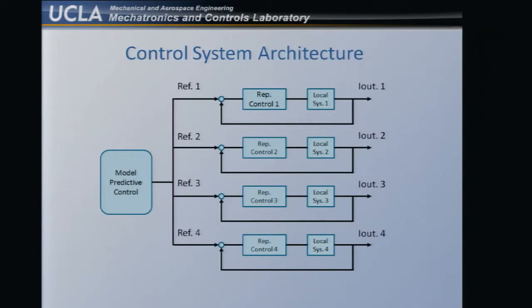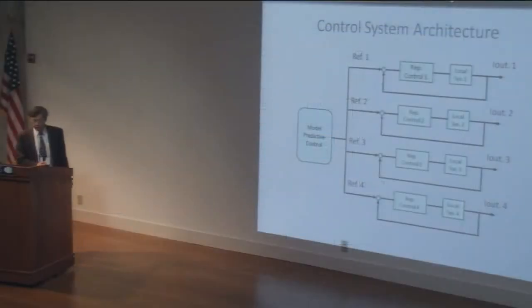In a sense, that control algorithm is able to do what the previous speaker talked about, like harmonic tracking and rejection of unwanted harmonics. In a more control block diagram flavor, this is the architecture we have. We have local DERs, each with some local power converter control. Then there is an upper layer control that controls how much power each unit should generate or take. That's the two-layer control structure.